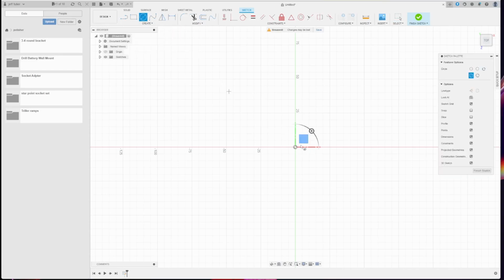Now, I know the exterior diameter of my pipe is going to be 0.630. We're going to type 0.630 and then we're going to put an IN after it because my sheet's actually set up in metric, but all my measuring tools are in inches. So I can leave everything in metric where it kind of works for my 3D printer, but put my dimensions in as inches and they'll automatically be converted.